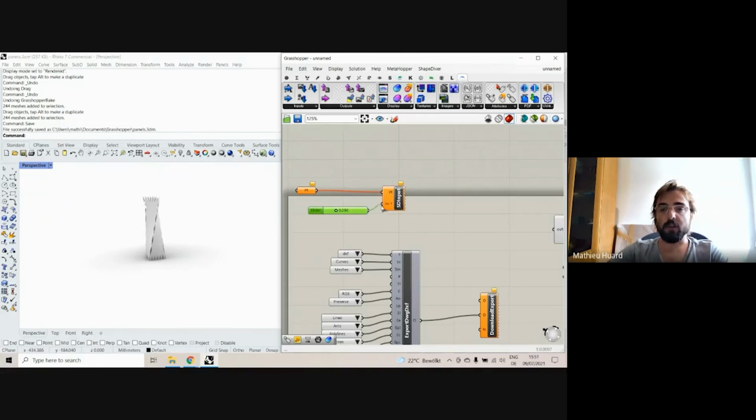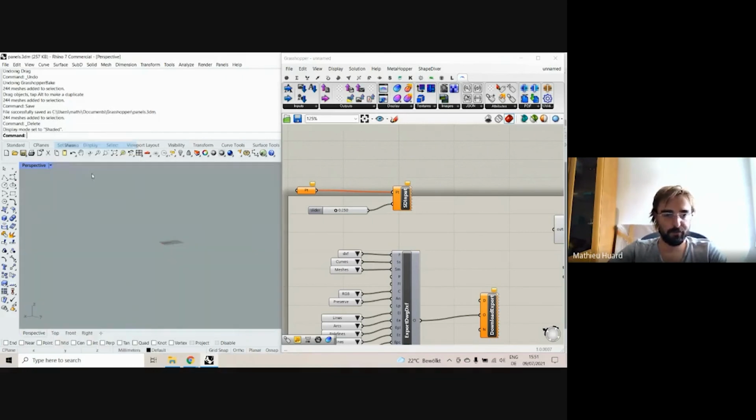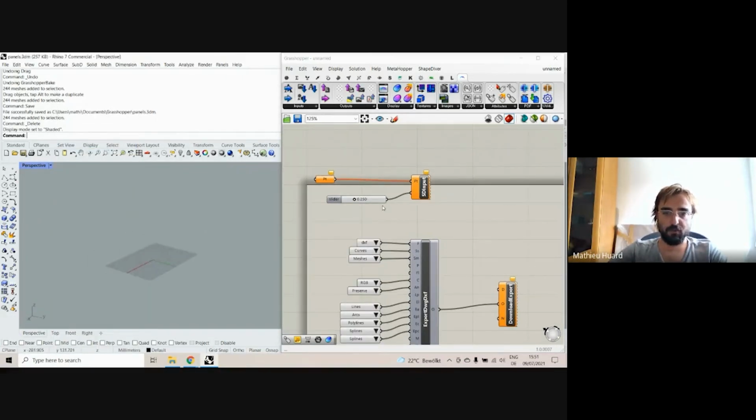And so of course, if you can upload that and access it through the Rhino clients, then in Rhino you'll have the inputs that we just showed. So you'll have those two inputs. You'll have the slider that you can move in the Rhino client, and you'll have the point, which if you select it in the interface, Rhino will prompt you to select one or several points in the document. Press enter, and you've set your other input, right?